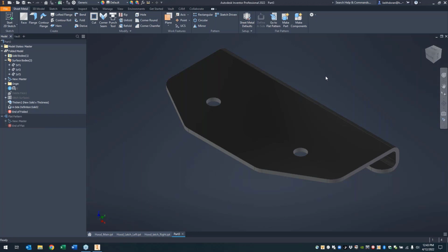And as far as the criticality of it, it really only depends on neutral format files more than anything else. Obviously when you create a base extrusion or use the face command in sheet metal, you're defining the normal direction of the part, and that in turn is telling it the A side or the inside face versus the outside. But if you're working with an imported object like this one or the IGES file, it has no way to define that, and it's just going to make its best guess. And if I want to have control over it, then I should definitely be picking, okay, this is the front or the A side model for calculations of neutral axis and bend orientation and angle.